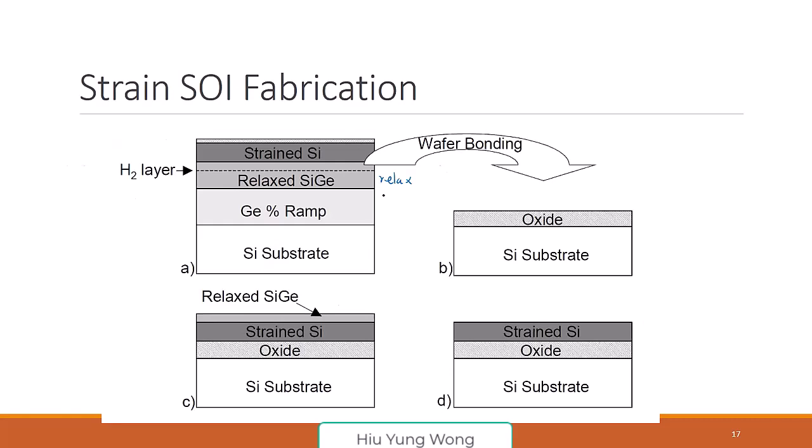It means they are at equilibrium position, right? This one has a smaller lattice constant. Then we gradually add them, and gradually it relaxes. And then on top of it, we put silicon because they're bulky, right? They are very bulky. So the silicon is under what type of stress? Compressive or tensile stress?